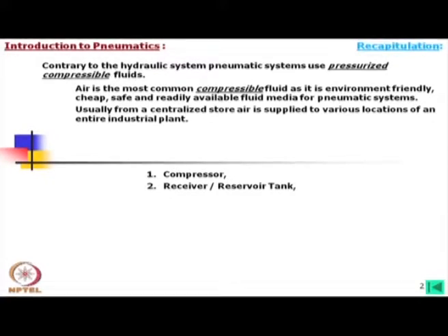Now, that air not only is compressed, it needs many other preparation processes before it is allowed to enter into a pneumatic system. First of all, this compressed air is stored, partially cleaned, in a receiver, which is also simply called a reservoir tank.